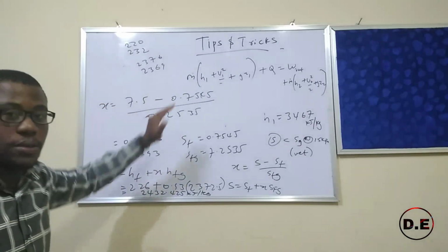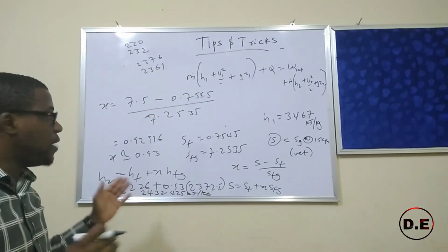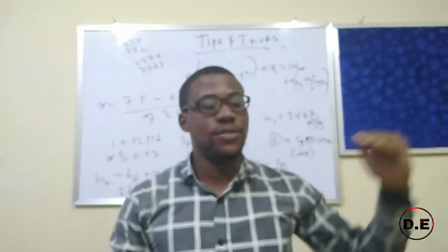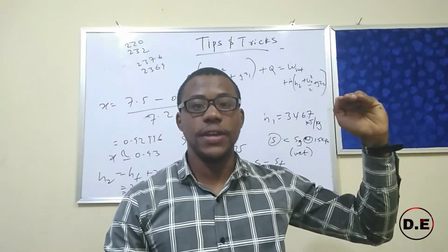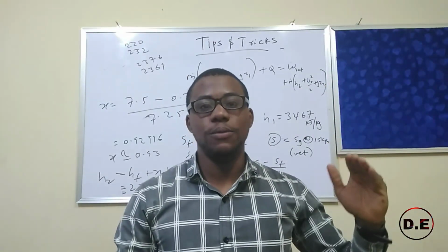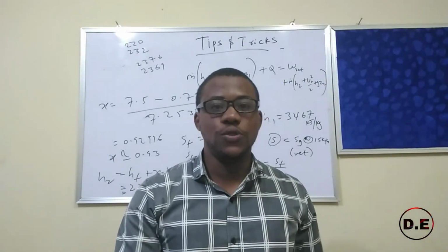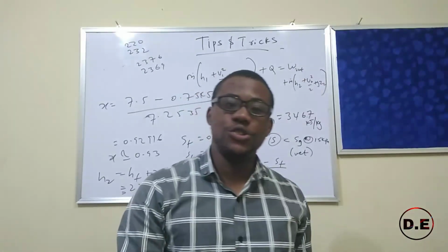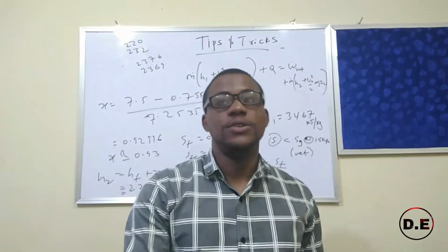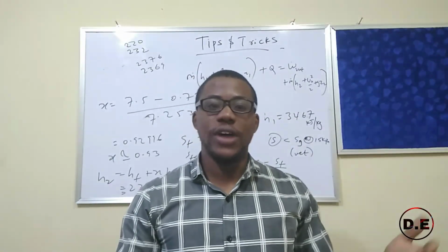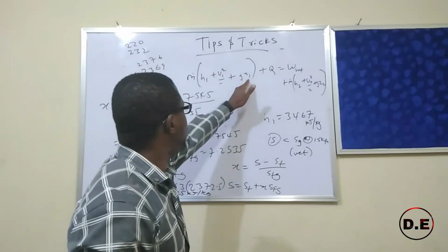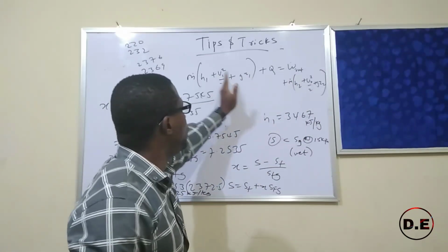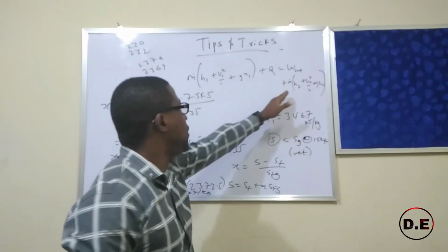So this is our h2, and that's all you need to know to analyze cycles where you are given entropy instead of the dryness fraction X. The rest is as we discussed in our previous video, where we talked about the steam cycle and analyzed the various velocities at inlet and exit. From the velocity, you can get the kinetic energy, which is v2 squared minus v1 squared divided by 2, and then the potential energy, which is gz2 minus gz1. Once you have those other two terms, you plug in gz1, gz2, v1 squared, v2 squared, and then you have your h value.